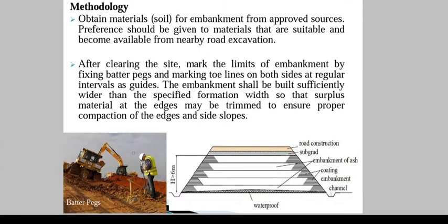each layer is compacted by using rollers, and compacted at the OMC, optimum moisture content. The embankment is constructed by spreading the loose soil and maintaining the OMC while compacting it. The compacted thickness of each layer generally varies from 100 to 300 mm depending on several factors such as the compacting equipment used, the type of soil, the density to be achieved, and any other